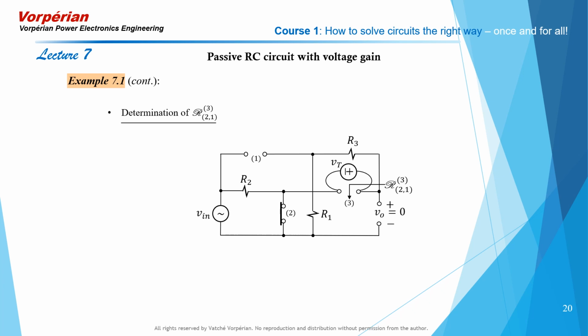In this case, you see that Vin has dropped out of the picture, and Vt itself is connected across R1 and R3. And regardless of the voltage V0, which really is Vt, that ratio of Vt to It, which is the impedance seen by this test voltage source, is nothing more than R3, R1.